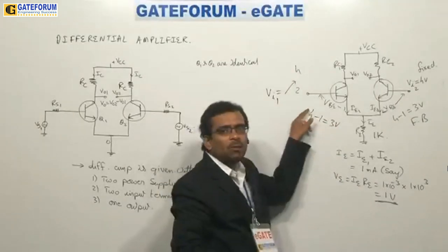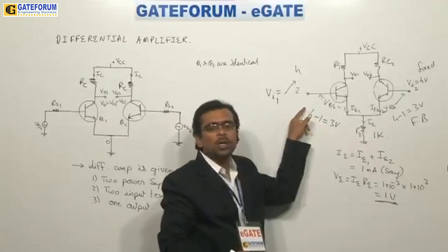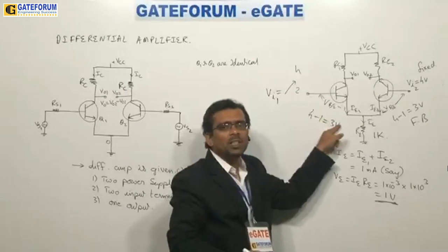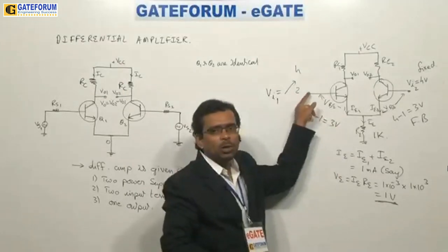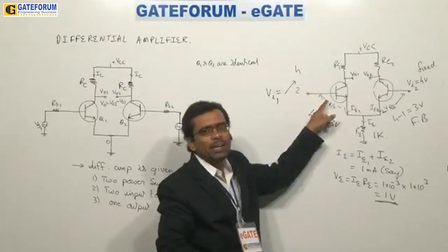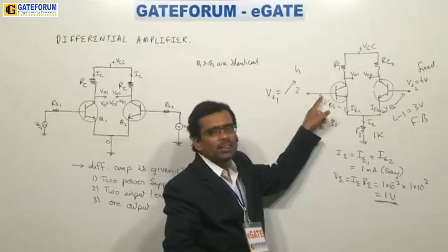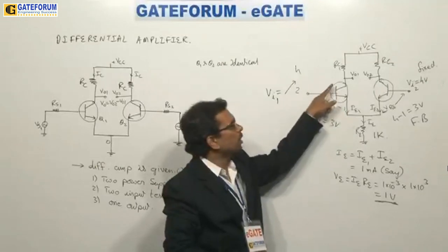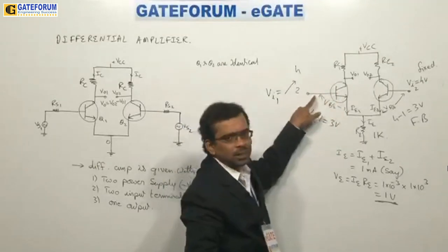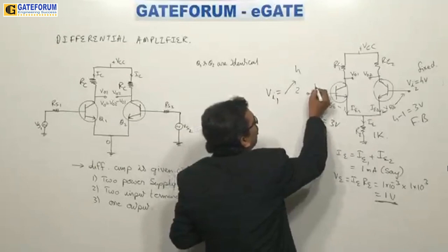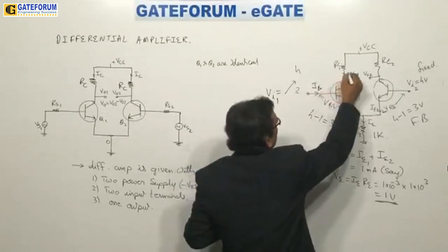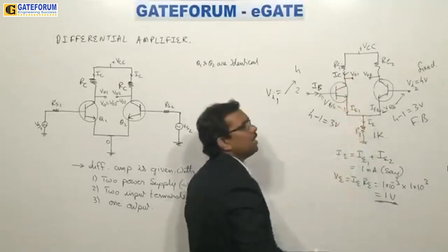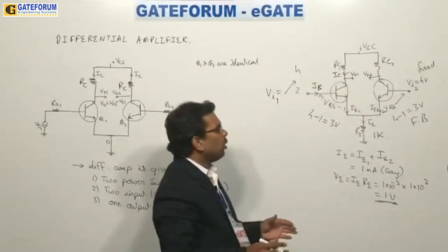Now this is forward biased. Because I have made this more voltage, this junction is more forward biased. When the base voltage increases, obviously IB current increases, thereby IC increases, IE also increases. IE is equal to IC. So you can see here that because of increase in base current IB, IC current also increases. If IC increases, IE also increases.